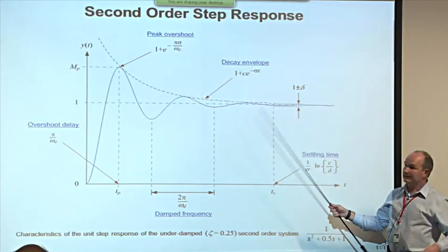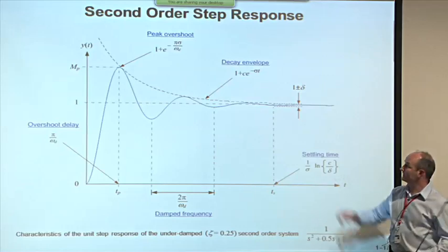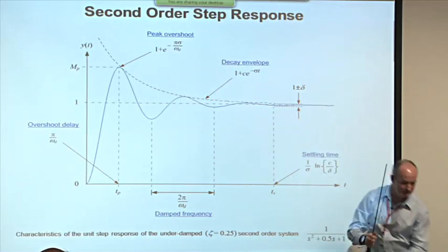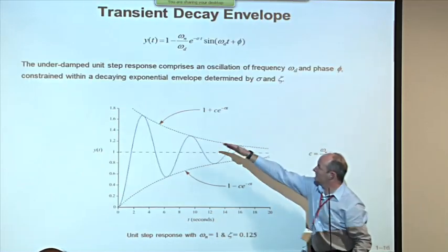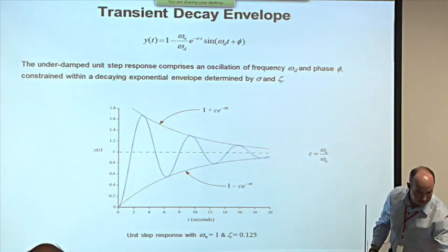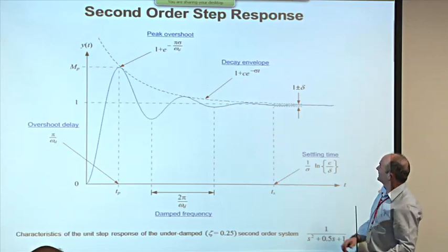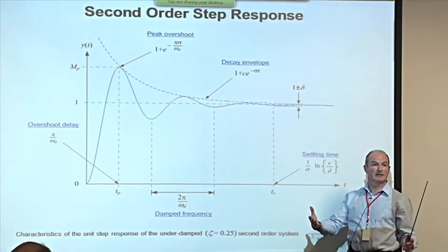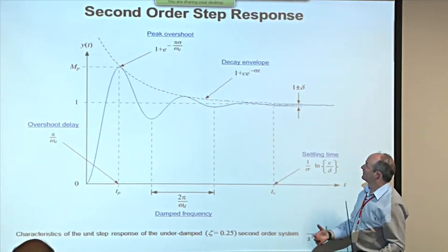And then whatever the oscillations are doing, they're never going to go outside the error band because they're constrained by this exponential envelope. So you look at the time that it takes to get there. Now, obviously, that's going to be pessimistic because all you're doing is guaranteeing that you've gone inside the error band.